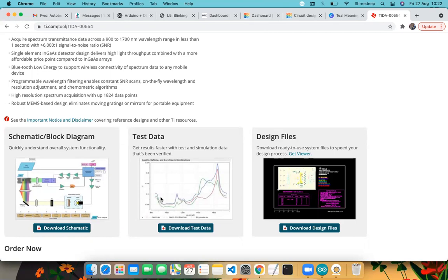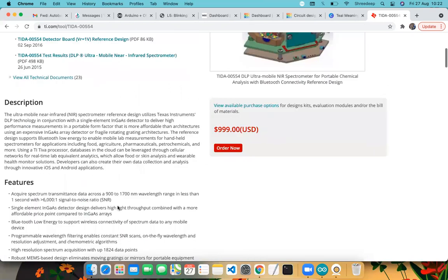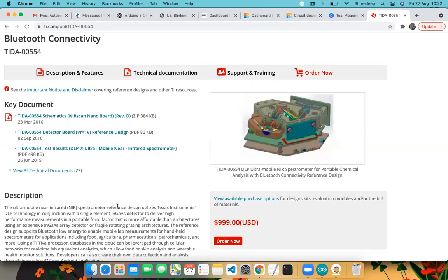So what can happen just by shining light on your skin? You can let this light interact with different biomarkers present in the blood, for example glucose, hemoglobins, and so on, and it can provide different scattering effects, which can be reflected to the NIRS receiver to see, okay, this is the blood glucose position, or this is the hemoglobin status, or this is the oxyhemoglobin status, right? One thing we have seen in the pulse oximeter technique, the PPG method, heart rate, that fingertip based PPG, photoplethysmography technique, which basically provides infrared spectroscopy.